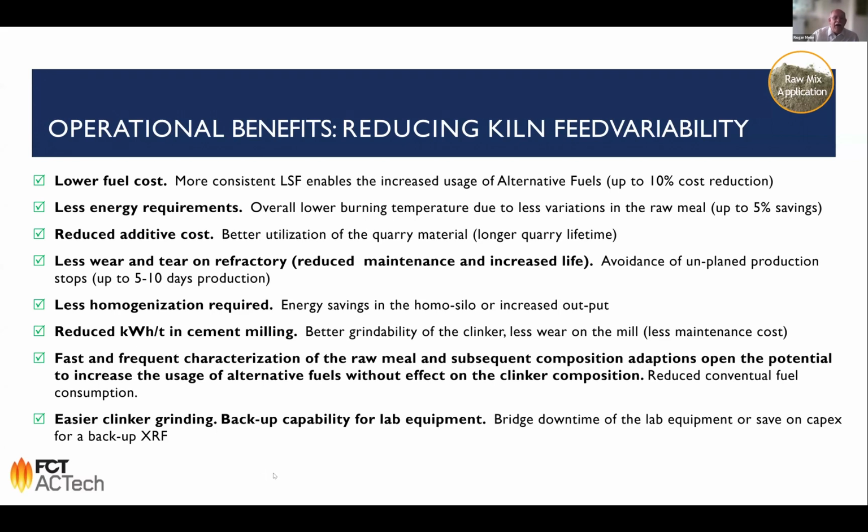I know many plants have very, let's say, good homogenization silos, etc. But of course, they are also requiring a lot of energy. And it might be one option, if you measure your raw meal quality more precisely and more frequently, that you can also save in these steps.